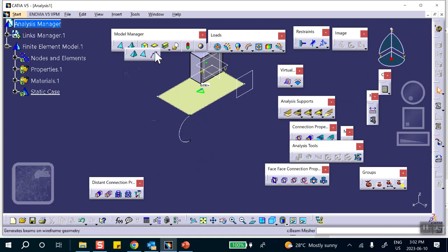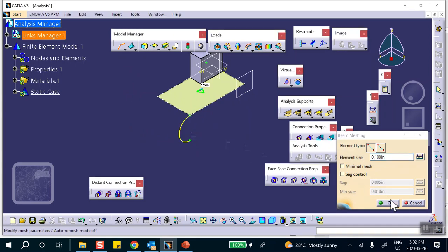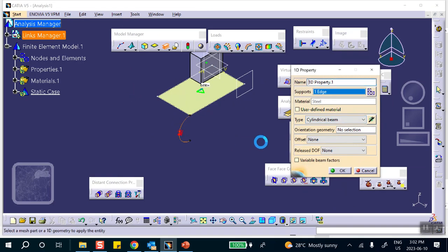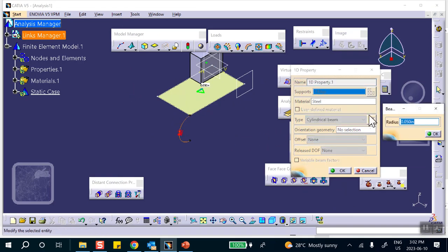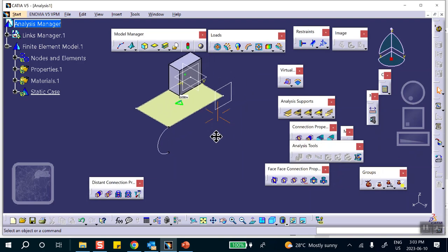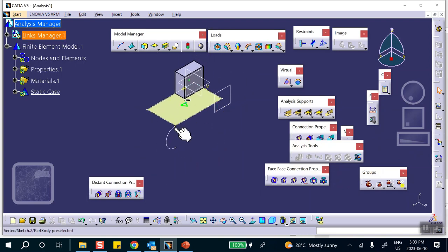So beam element right there, and we give it a circular, cylindrical cross section, and the radius according to the drawing is 0.025. Remember, this is not a cable. It is a perfectly welded structure. It's not a cable. Cables can't hold up things like that. Good. So that's pretty much it.